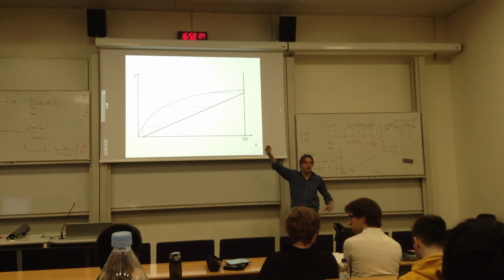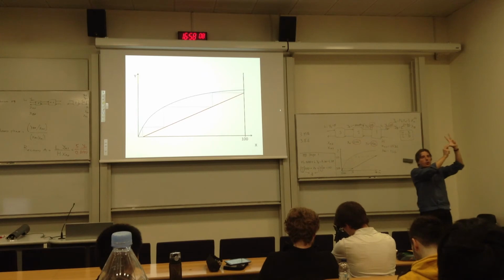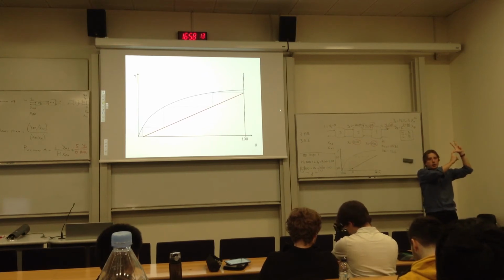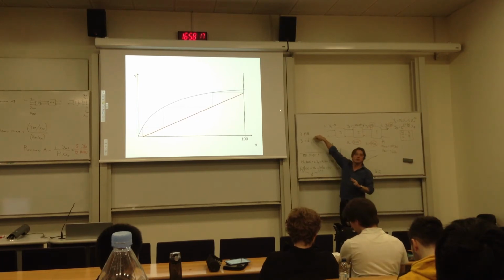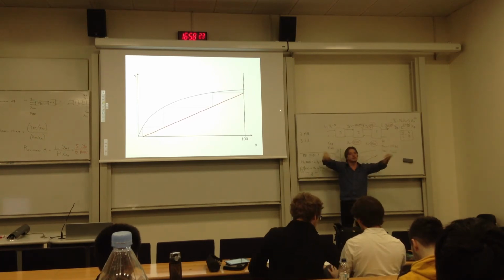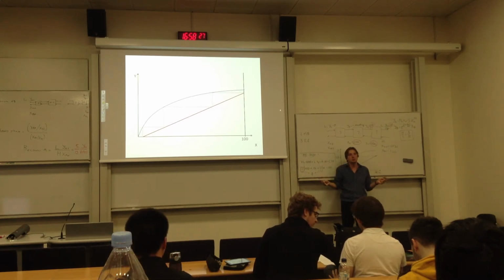So again, there are 3 ways of solving this problem. The Kremser equation, which we couldn't apply because we didn't have a constant m. Writing the mass balance and the equilibrium and solving mathematically a system of 6 by 6 or whatever number of equations.